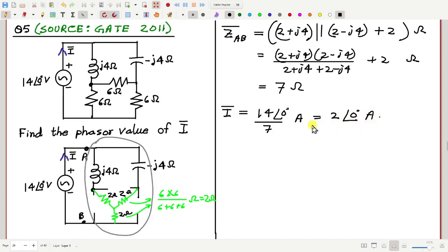Okay, so can we have the balanced Wheatstone bridge in this condition? We don't know whether this looks like a Wheatstone bridge, but whether it is balanced or not, I mean, it's not balanced actually. No, because there is minus j4 over. Yeah, right. So if you take the ratio of the opposite arms, you will see the ratios are not equal. I mean, the ratios of adjacent arms.